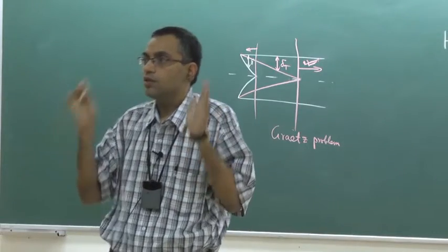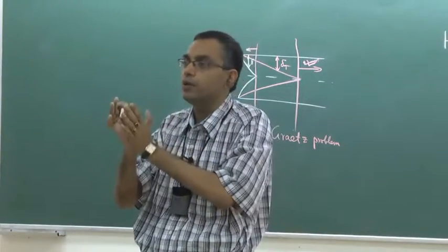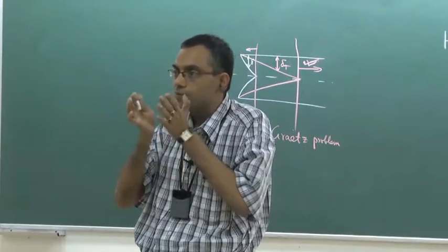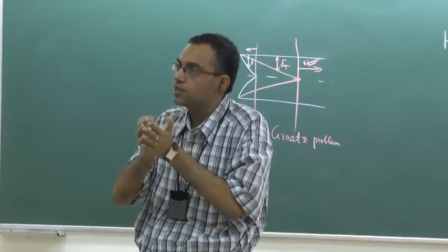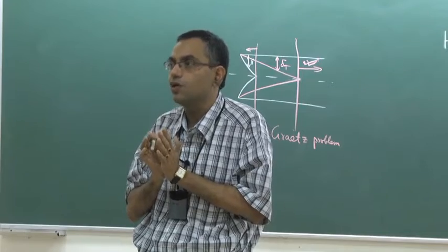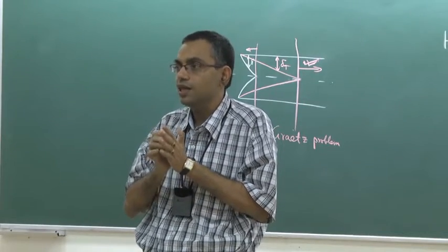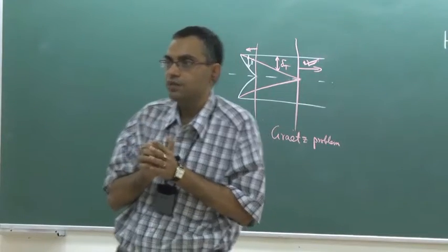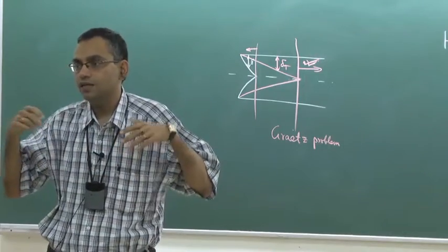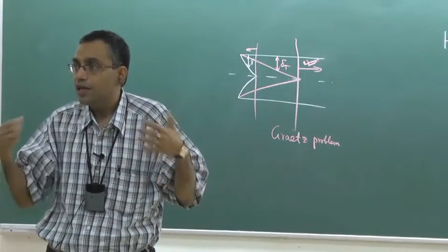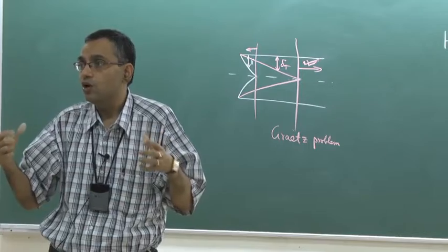But for hydrodynamically and thermally fully developed flow, for internal forced convection, that is a special case where the Nusselt number becomes a constant. But in general, the situation changes if the flow becomes turbulent from laminar.